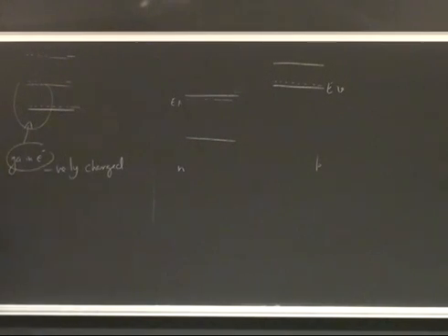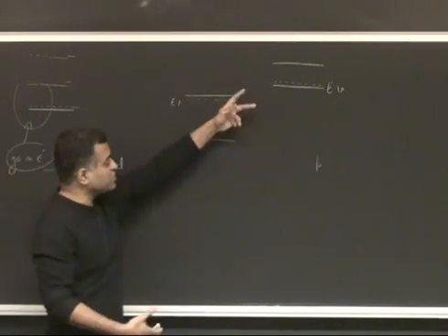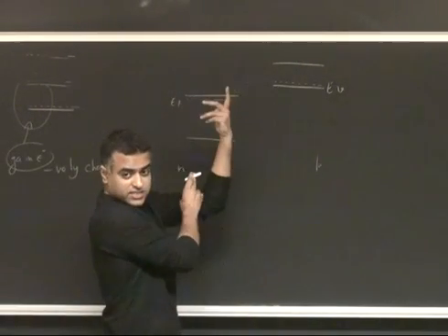So that thing happens in a heterojunction. In a homojunction, this can never happen. So in a homojunction, if you have an N layer and a P layer together, the N-type layer will always lose electrons. The P-type layer will gain electrons. There's not much to do after that. But in a heterojunction, by choosing the right band alignments, you can completely change the game.